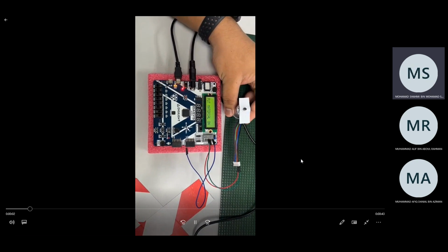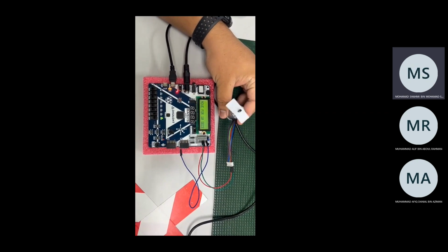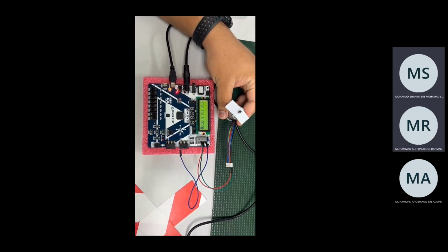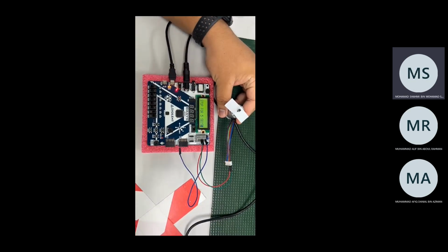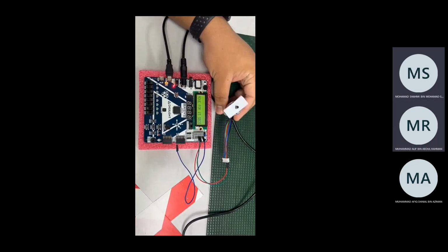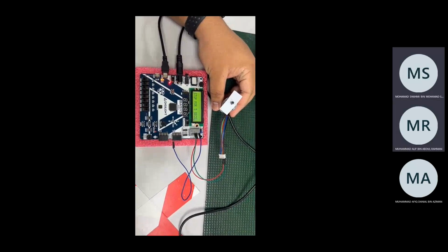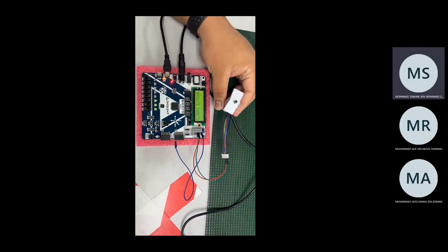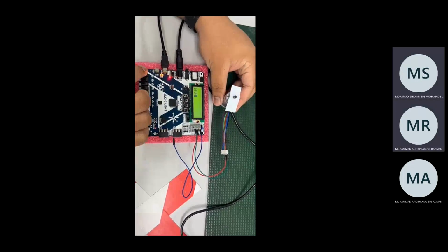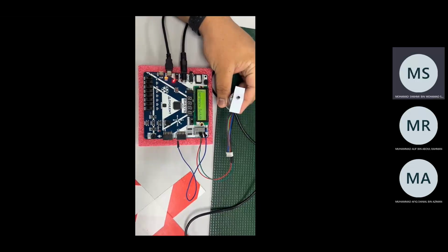So this is the first step. Put material on the conveyor and then it moves for 10 seconds. And then it will stop for 5 seconds. And then it will move in the opposite direction with 3 LEDs blinking. And then it will stop the process. The last one is for the emergency switch.